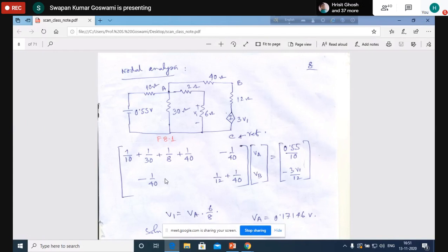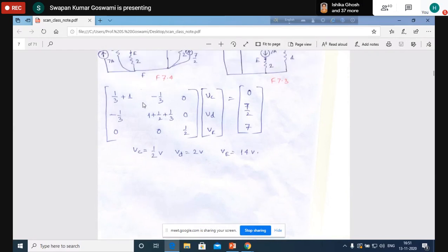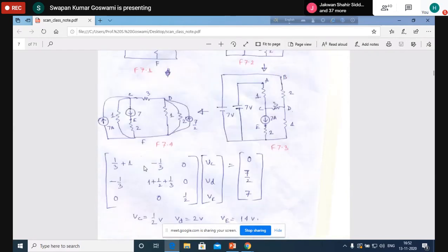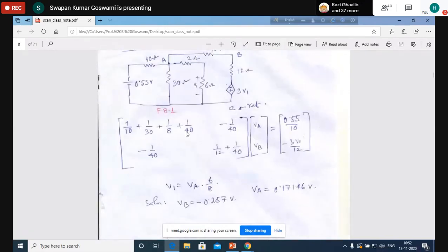All right. Now why is the matrix no longer symmetric? Who is responsible for that? Previously, whenever we had written, we always had the symmetric matrix. Here you see that Z12 equal to Z21, Z13 equal to Z31, Z23 equal to Z32. It was there. Now in this circuit, Y12 and Y21 are becoming different after this modification.